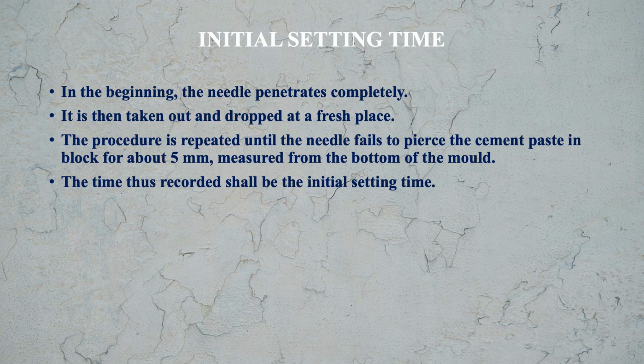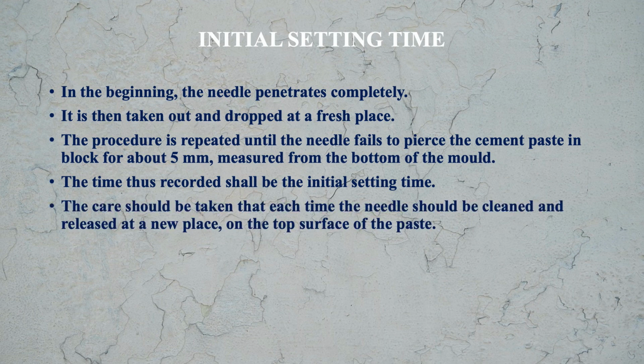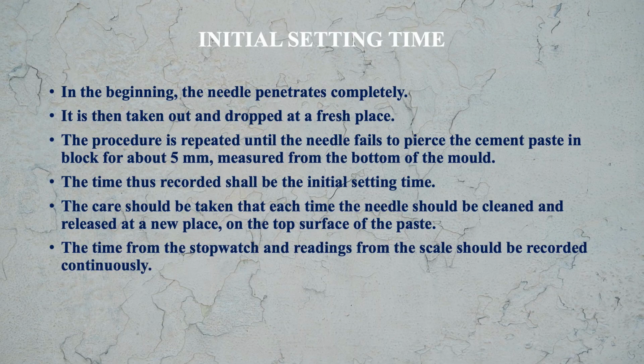Care should be taken that each time the needle should be cleaned and released at a new place on the top surface of the paste. The time from the stopwatch and the readings from the scale should be recorded continuously. So that way we do this initial setting time test. Now let's move to the final setting time.